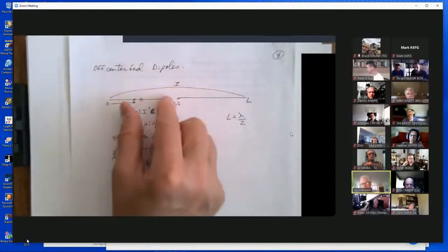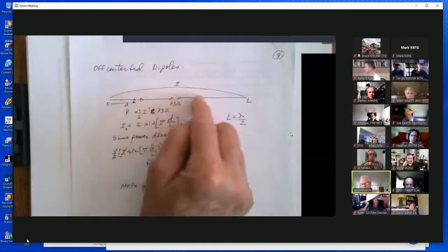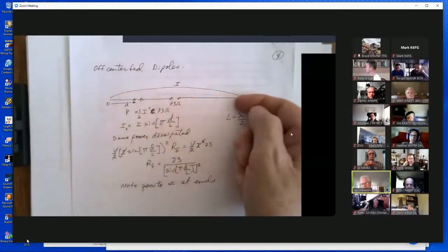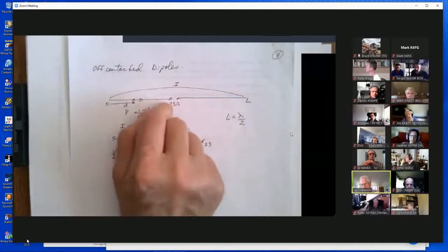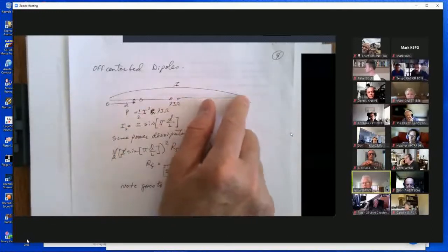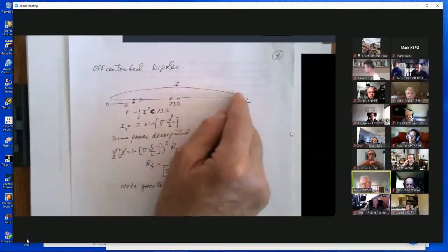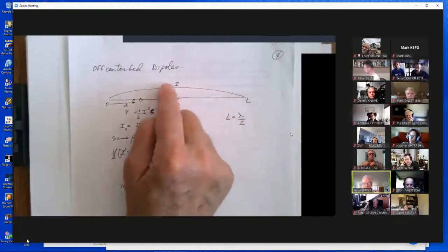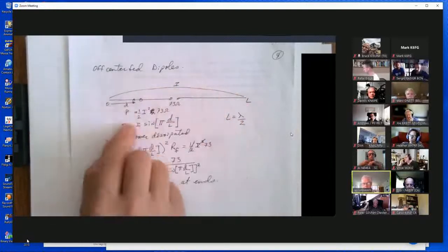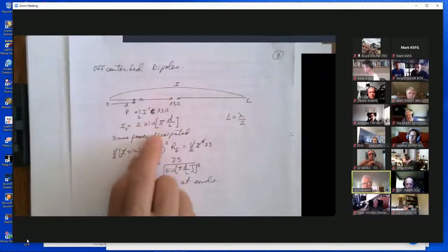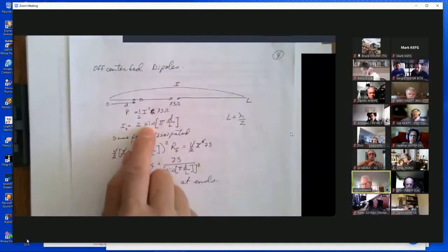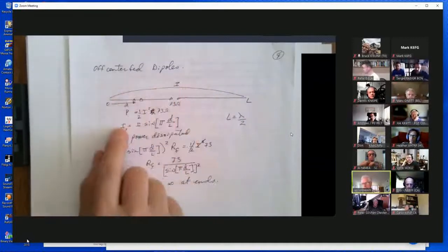One of them, you can look at this as an open transmission line. You're sending out current this way, it hits the end, and it has to turn around and come right back, okay? And it's out of phase. And so at the end, it exactly cancels to zero, and as you come back, it starts to add, so you get the maximum current in the middle. This current will have a sine distribution, basically, very close to it.